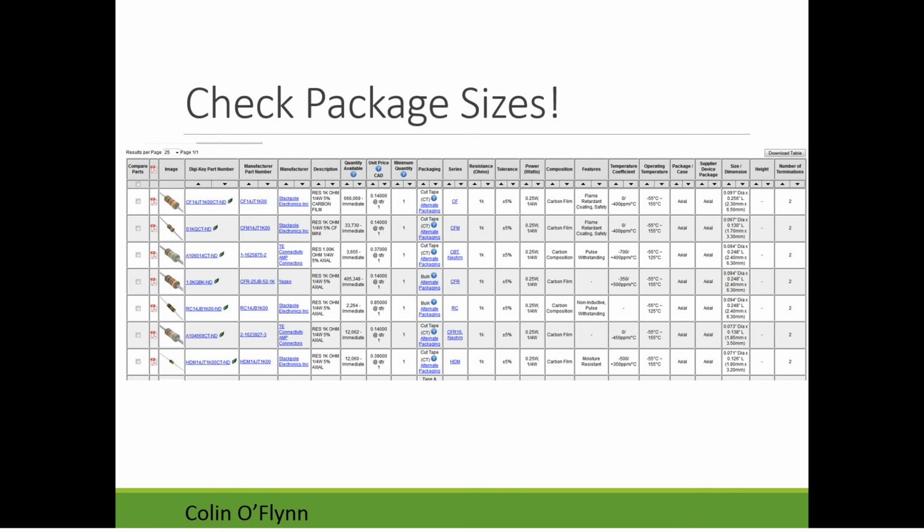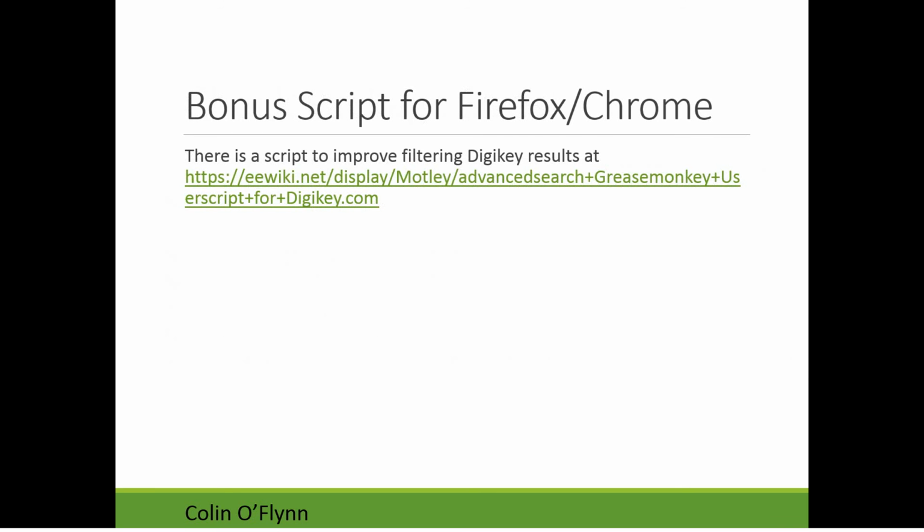So we might finally have to say, okay, what's the package size? We can see the length of the resistor. Some of them are like 6 millimeters long, which is a normal length. Some are only 3 millimeters, a little smaller. You would just have to look through and say, what is the difference between these 10 options? Is there anything I care about? Sometimes you don't care about the difference, so you just pick one randomly. In this case, we would choose a package and add it.